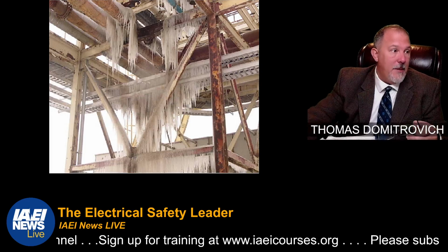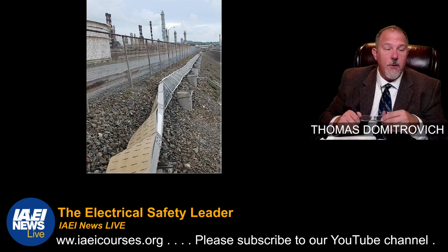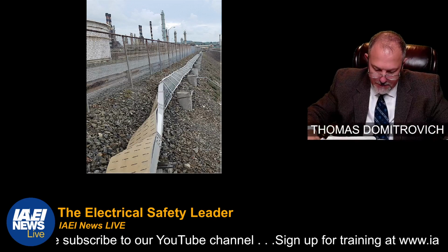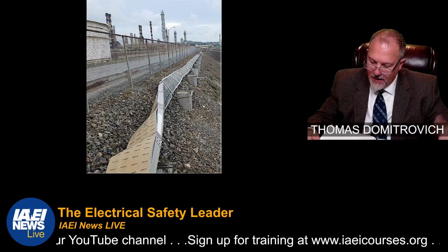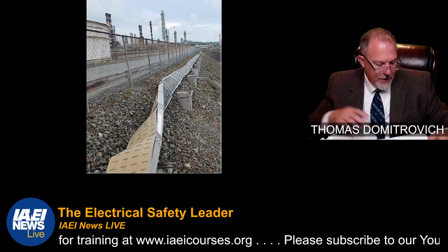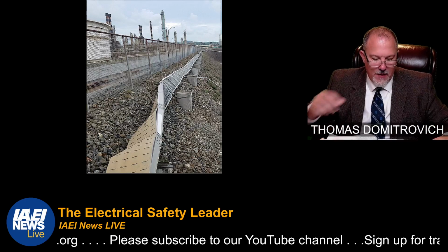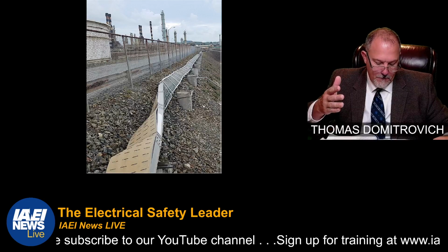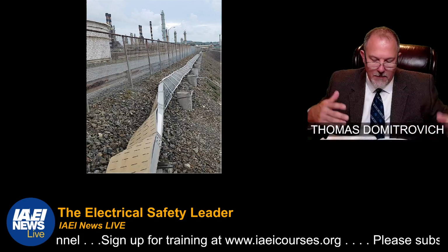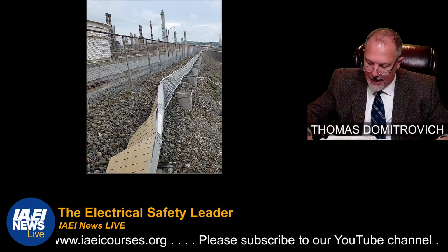You've got to think about wind. You've got to think about the wind load. Most of your outdoor cable tray systems are going to experience wind, and you have to design for that. There's not going to be anything in the National Electrical Code. I mean, they'll tell you to install per manufacturer's instructions, but they're not going to tell you how to calculate wind load, right? They'll tell you to make sure it's braced, make sure it has access, make sure that it's marked, all that jazz. But you're not going to sit there and say, hey, make sure it's rated for the wind. You have to make sure that it's installed per manufacturer's instructions, and you have to consider all of these applications.